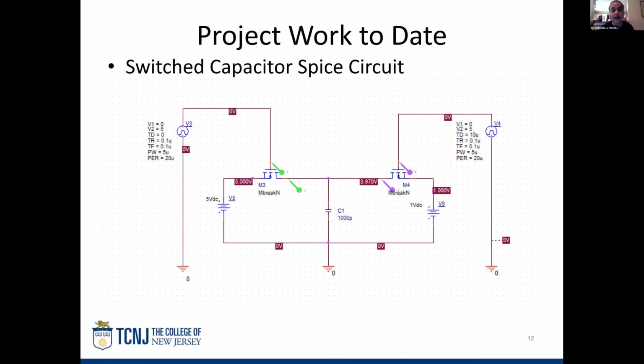Yeah. So that allows you to discharge the capacitor completely, and translates into a better current output. Okay. So you don't have an offset, because with this you will have an offset. I mean, in SPICE you can discharge it, but in real life you're going to have some type of offset, which translates to an error in the resistance, because the equivalent resistance is the period over the capacitance. Right. Okay. That's all my comment.